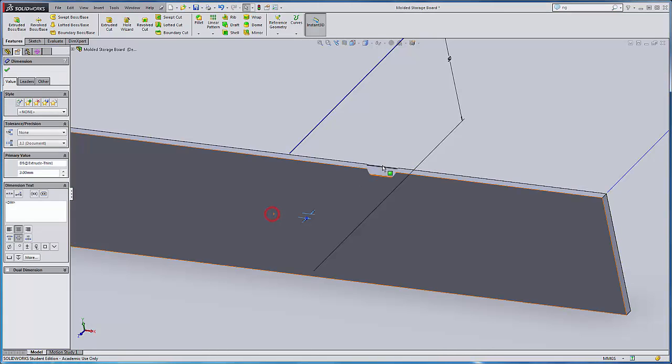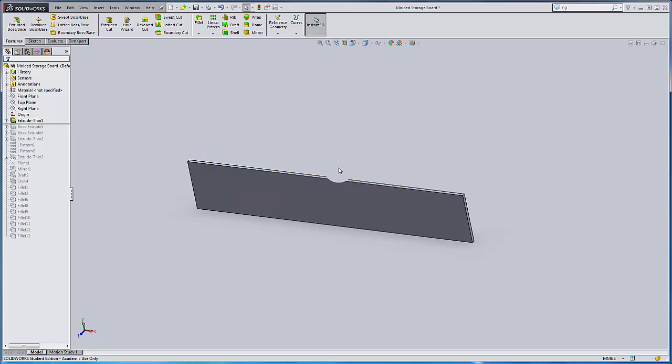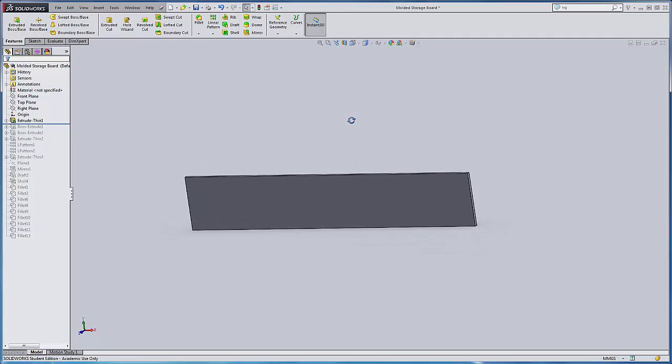3 millimeters thick. Now, that's another thing you need to know about injection molding of plastics, is that it likes to have similar size, if not the exact same size, wall thicknesses everywhere. And usually those wall thicknesses are best between 50 or 100 thousandths of an inch, or in this case, about 2 millimeters. Well, I made it 3 millimeters, which is a little bit larger, but that can be done.